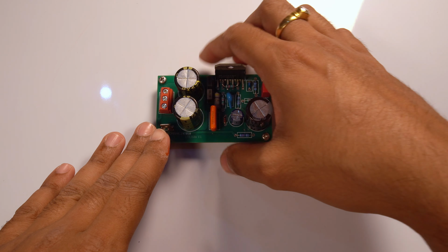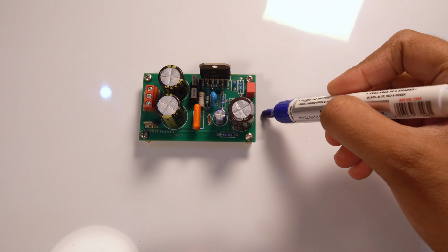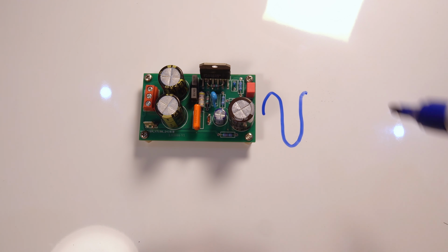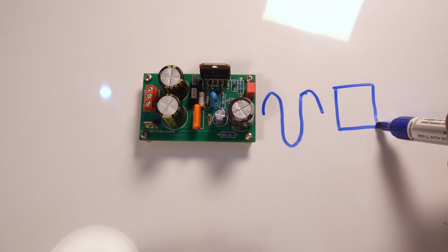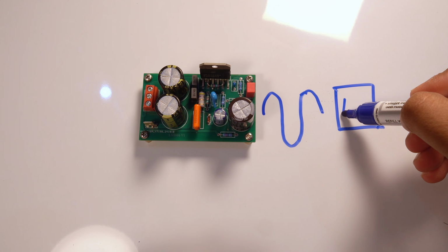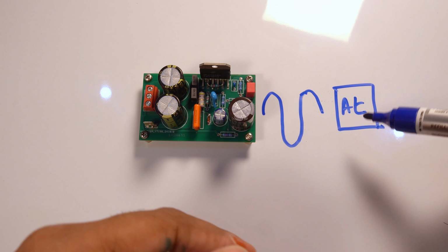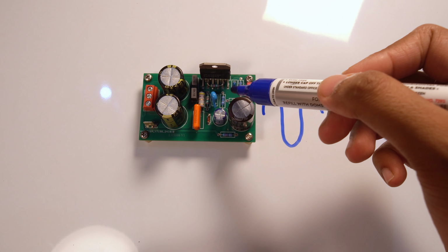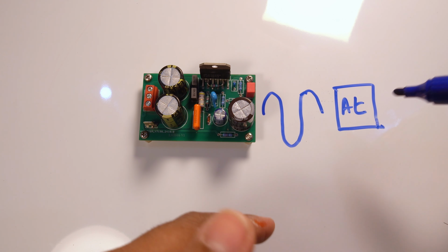Now the only thing remaining is that we are going to have our amplifier in here, and that is going to provide the output sine wave, which is going to be attenuated down, I will say AT or attenuator, because obviously I cannot use my sound card directly on the output of this amplifier, which will just burn the ADC inside the sound card.